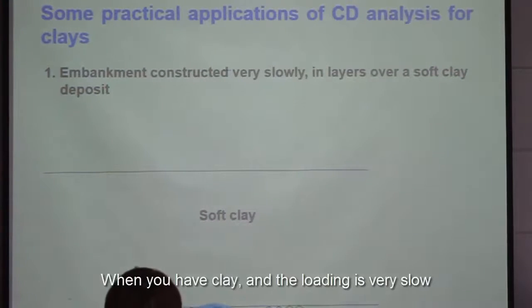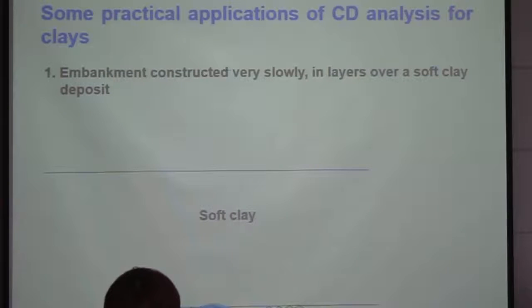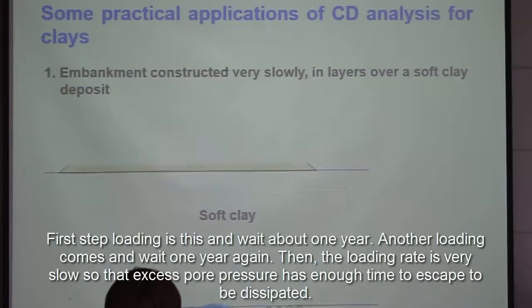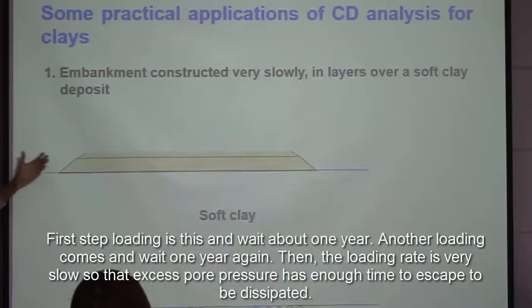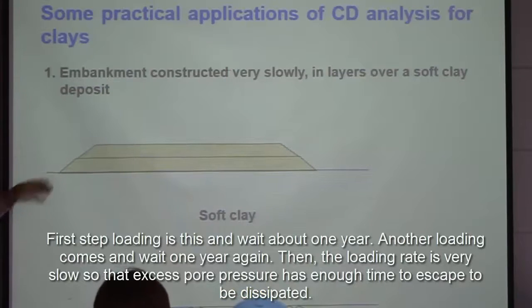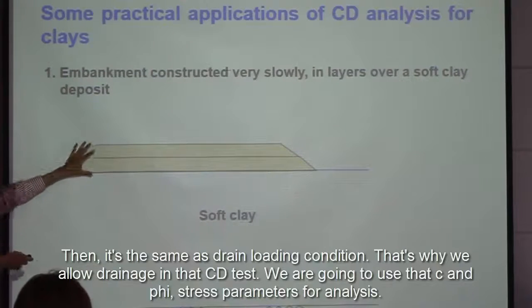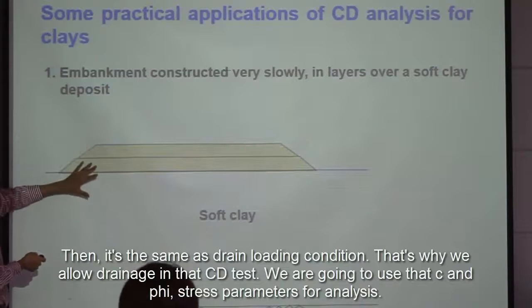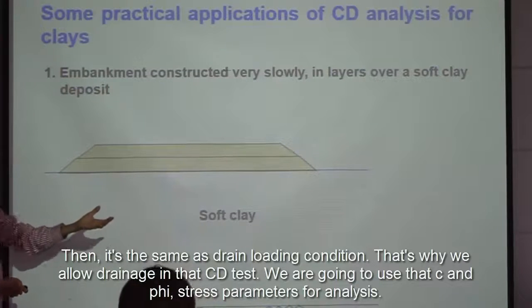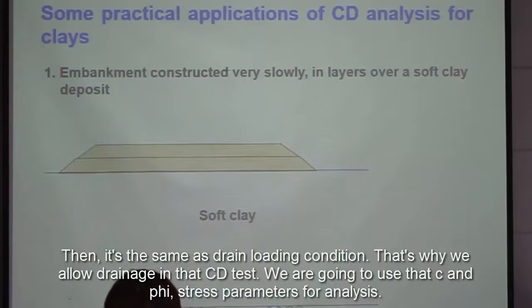When you have a clay, the loading is very slow in this case. So the first step of loading is applied and you wait about one hour, one day, and then another loading comes and you wait another day. Then the loading rate is very slow, so that the excess pore pressure has enough time to escape, to be dissipated. So then it's the same as the drained loading condition. So that's why we allow the drainage during the CD test, and we're going to use that c' and φ' parameter for this kind of analysis.